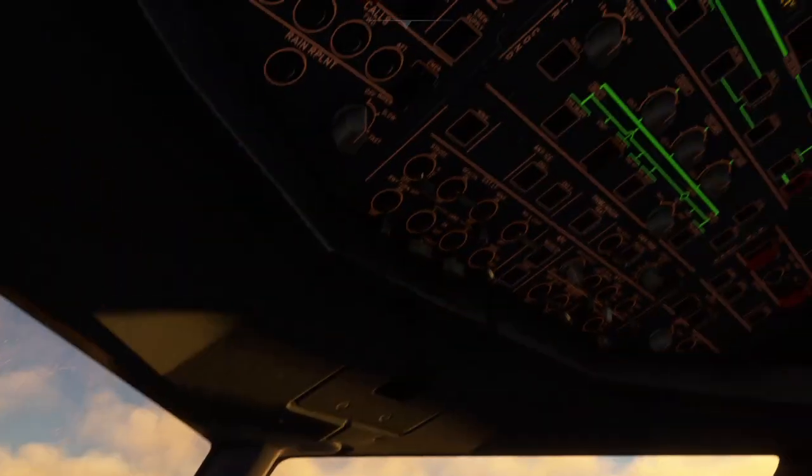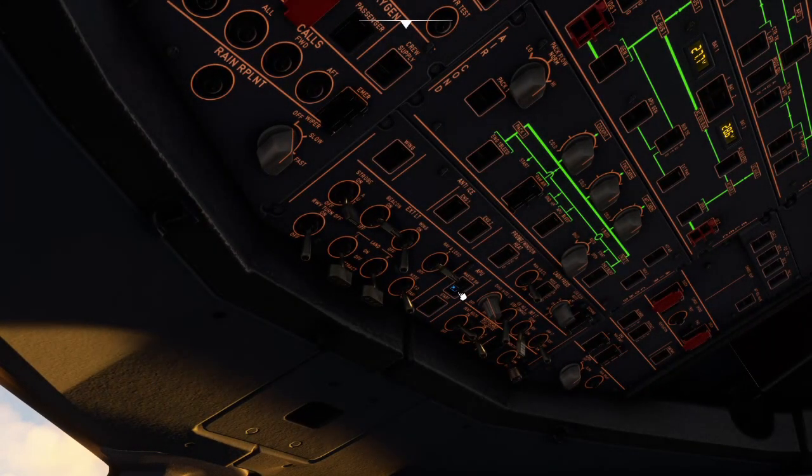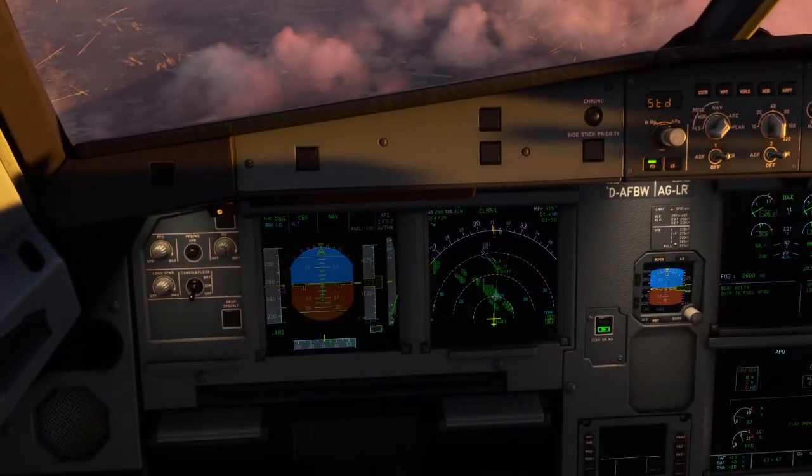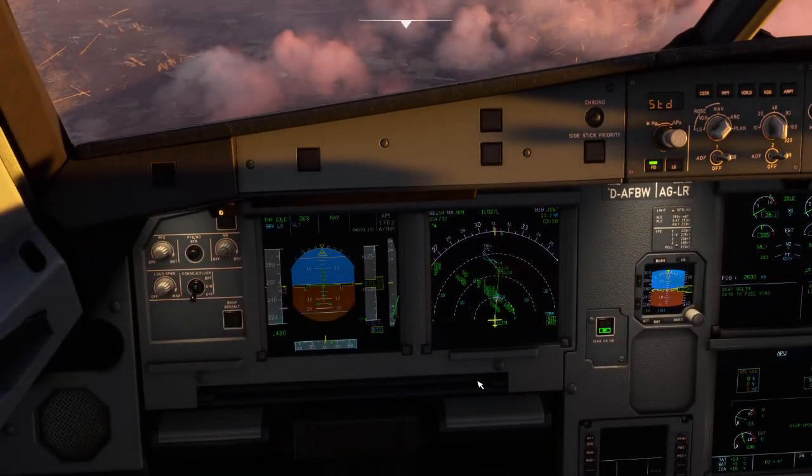Habit I have just from other airplanes I've flown, again, you don't have to do this. I find I don't have a real co-pilot to do this for me on the ground. I just like to start the APU now, so when I'm on the ground, I can just worry about taxiing and not have to worry about trying to look around starting APUs. I'm sure in the real world, you would just do that on the ground taxi again like other airplanes. Just depends.